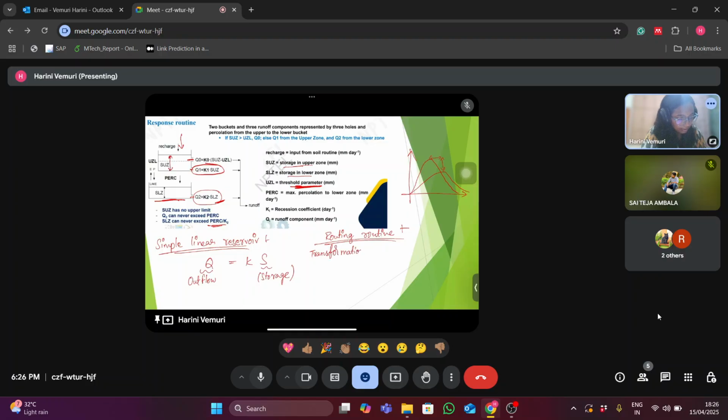In this they use a transformation function in which the generated runoff of one time step is distributed over the following days using one free parameter, MAXBAS, which determines the base of an equilateral triangular weight function.